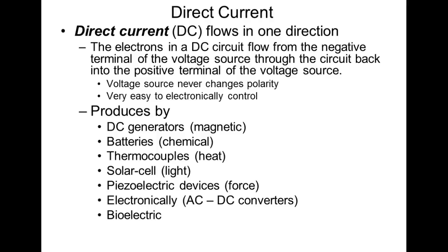Okay, so now we know the difference between an open and a short. In cable splicing and installation, you're either going to create opens or shorts by incorrect termination or incorrect splicing, or putting too much stress on the cable. The name of this course is Cable Splicing and Installation. They left off the termination, but we got to teach that too. With installation, a lot of times we pull these conductors through tubes we call conduit, which we'll talk about later on. And if you don't pull them right, what could you do? You could stress the conductors and break them. I've seen people break conductors all the time trying to pull them.